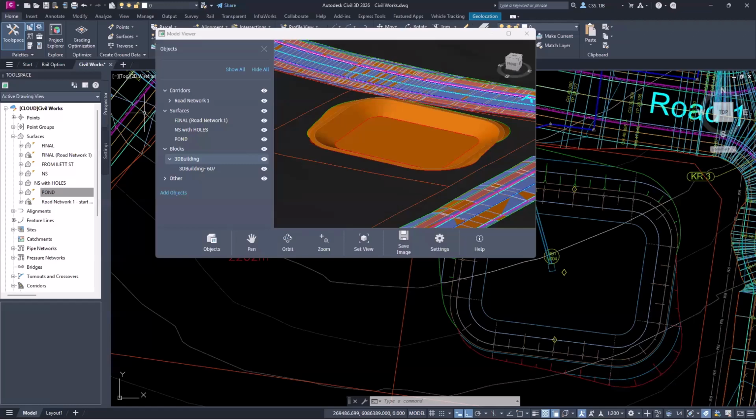There's no fancy tool. If you did want to do that, it would probably be better to do it as some sort of COGO point, because then you could set the COGO point to drape off the surface and have the label be the lot number. Then you would just have to explode that back to being a piece of text. It should be at the right elevation, and you throw it in. That's probably the one thing I could think of. But no, I did have to manually set all the levels on those things, which was a bit tedious.